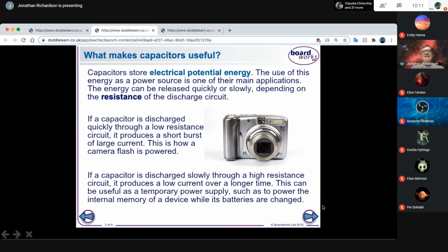So we use stay alive capacitors, just like these, connected into the motor. And they are connected over the side of the motor. So when it loses its electrical contact, the power that's inside here goes into the motor to keep it running.